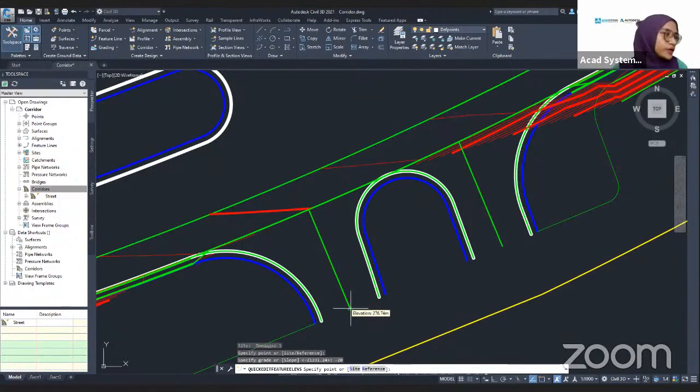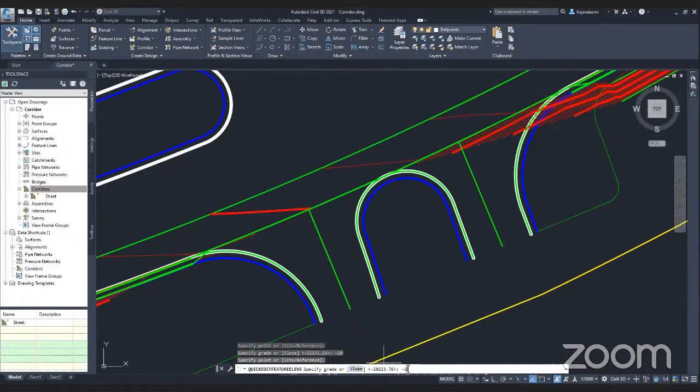So the elevation has been fixed, and then the similar one for this one area. Okay, just going to select again -20 there. Enter again, and then we now have our elevation. All right, so for now, this one is still 0. So I'm just going to copy from the existing one here, 276.74. So I click again on this line, and I'm going to put in 276.74 for the elevation on that very end line. Okay, so this will be similar again, 276.74.